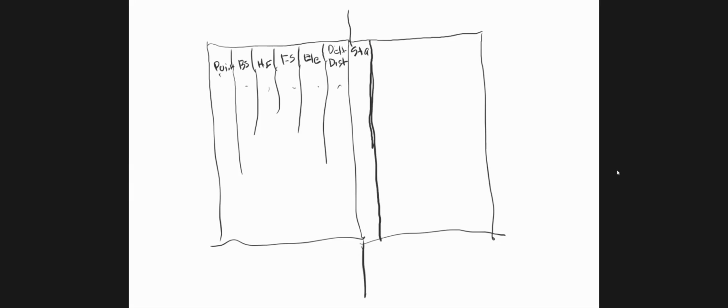That will be on the right side of the page, which will mean you have less room to draw your sketch information, but you can fit it all still on the right side over here. You'll just have a little bit less room across the page because you're adding this station column on the right side of your book. Okay, make sure you line up the distances vertically.